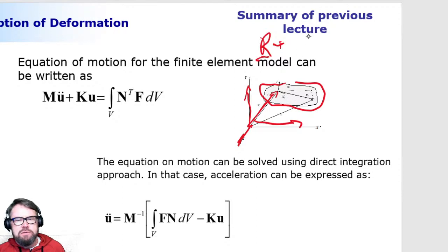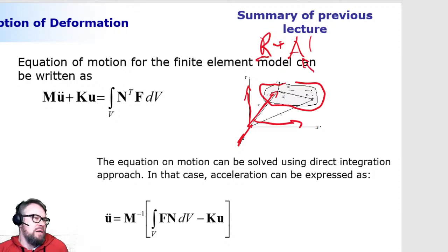The next thing to do is take the orientation of the body reference coordinate system into account. That is carried out by a 3x3 rotation matrix. There are many different options for describing this, including the ones we learn in this course: Euler angles, Euler parameters, Rodrigues equation, and many others.